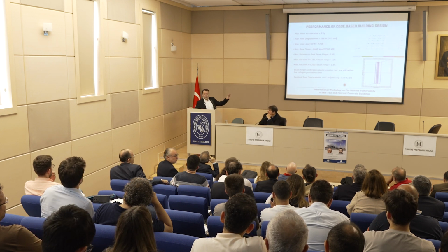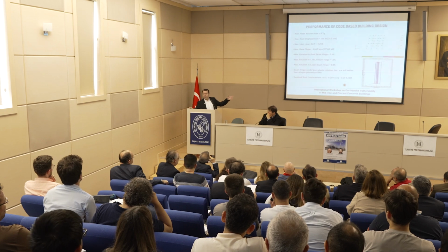In terms of this, let's start with the estimate of the residual displacement, which I think is a proxy for the question that you're asking. For this code-based design, we would have 0.5% residual drift at the end of the earthquake, right? And for the objective-based design, we have 1%.